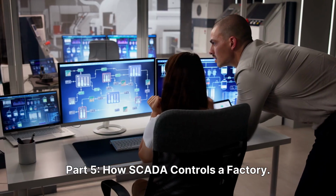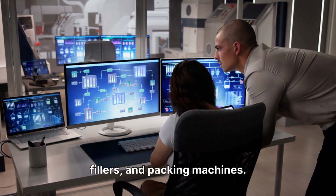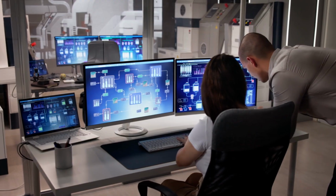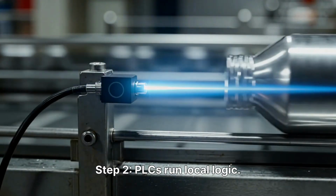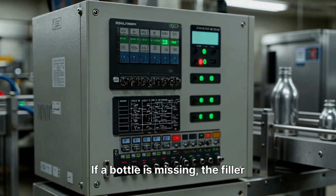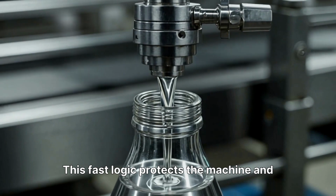Part 5. How SCADA controls a factory. Let's take a bottling plant with tanks, fillers, and packing machines. Step 1. Sensors collect data on levels and flow. Step 2. PLCs run local logic. If a tank is low, it starts a pump. If a bottle is missing, the filler stays closed. This fast logic protects the machine and production.